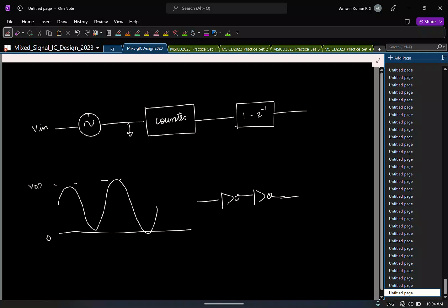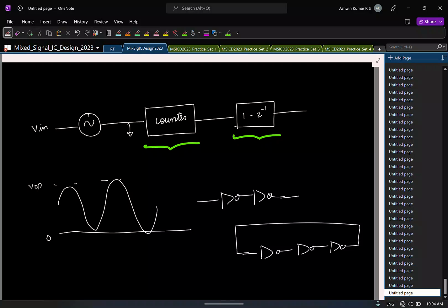And you see what are the things you need, right? You just need this guy, and this is a simple digital subtractor. Take the digital input, take the previous digital input, subtraction, trivial. Counter, second year you know how to do it. And this VCO is the only thing that you might not know. You know what is the simplest oscillator you can make? From inverters only. You can have an odd number of inverters and put them in feedback. This works as a simple oscillator. And to control the frequency you can do a lot of things, and it's pretty straightforward.